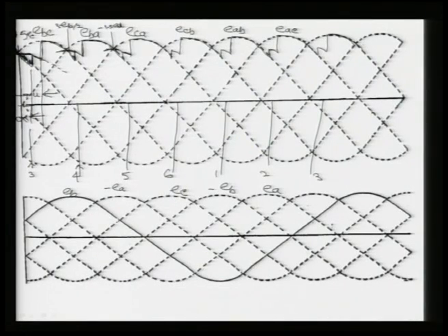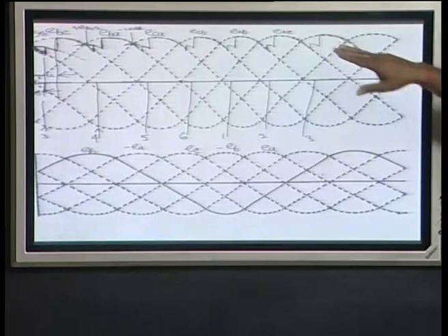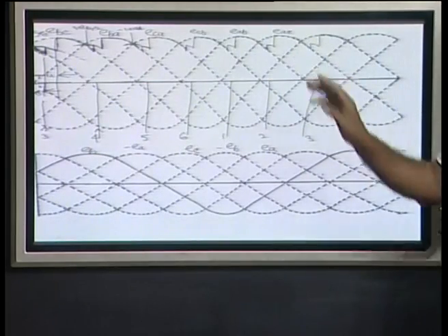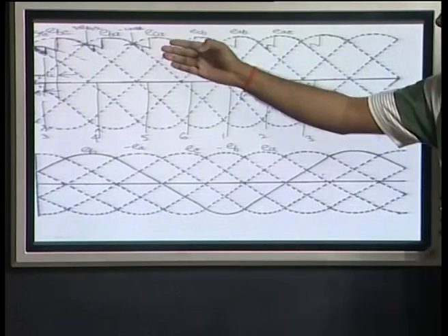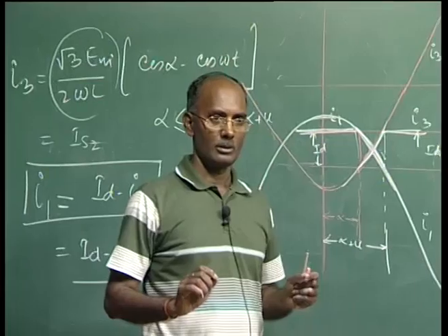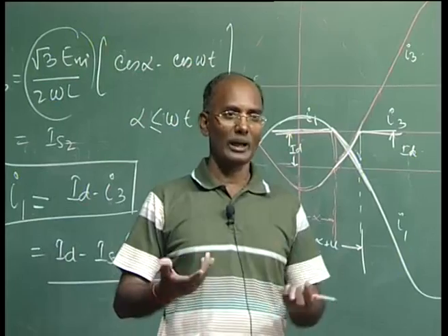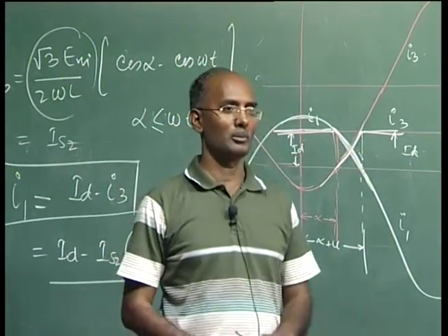Now similarly we can draw here. I want to remind you that this voltage concept must be very clear to draw the exact wave shape of the output. If you make any mistake here, you will get a different output. No doubt you know the sequence pattern and how it will come, but sometimes in inverter operation there is a commutation failure, and at that time you will find it is not symmetrical, and then if you do not know the voltage, you cannot draw the output voltage.